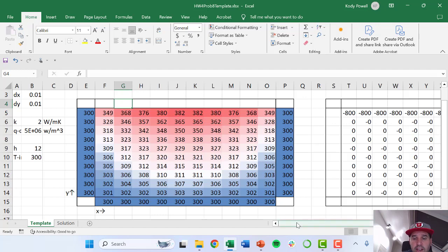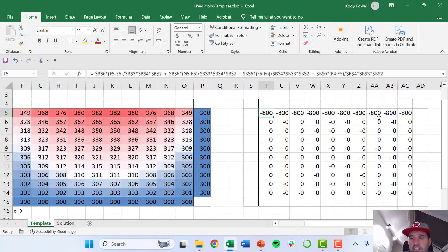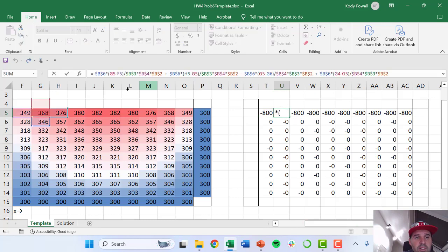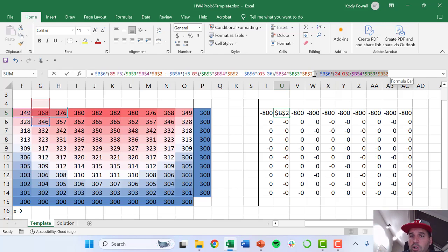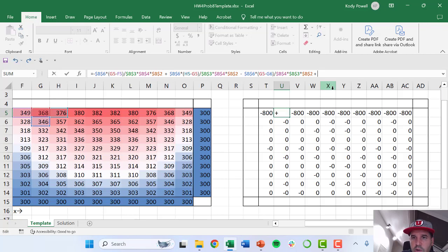So the way that I can do that, I can go to all of these cells that are touching that top surface boundary, and we don't want these to be referencing the temperature here anymore. Rather, let's just assume that that top surface is now very well insulated so that no energy crosses it. So if you recall, we would want to go to what we were calling our Y out term, which is here, and I can just put in a plus 0 there. So instead of conduction crossing that surface, we're going to have nothing. You can also just delete the term entirely.